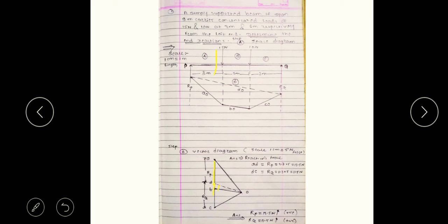Second force is 10 Newton. Again the second force is indicated by the line BC in the vector diagram. So come to the vector diagram again. In the vector diagram we know the B point already, so draw the B to C line, because this line will also be vertical, because the 10 Newton force is also vertical. So take the parallel in the downward direction, because both forces are in downward directions.